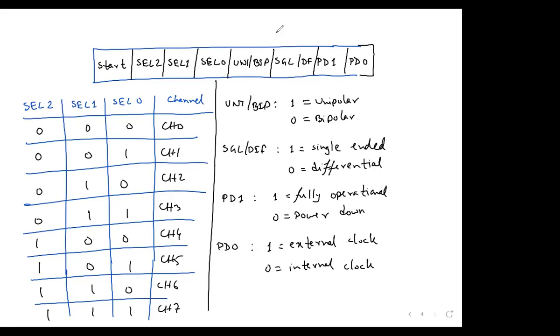All right, so I think this is quite straightforward. This pin, the MSB, should always be 1. There is no confusion about that. Then we have these 3 pins, which are responsible for selecting which channel you want to use. We have 8 channels, and the corresponding addresses of all these 8 channels are given.